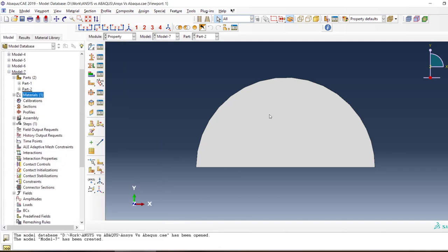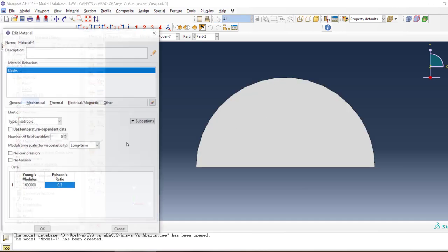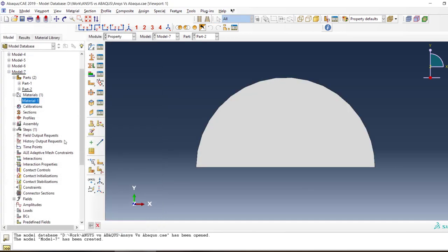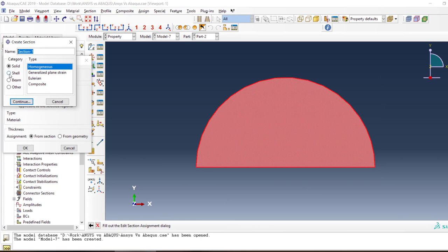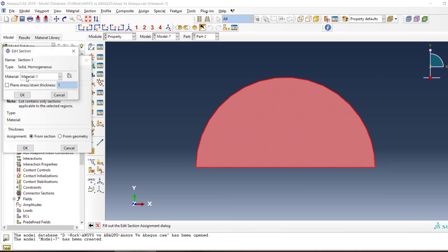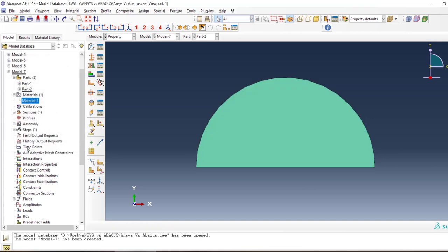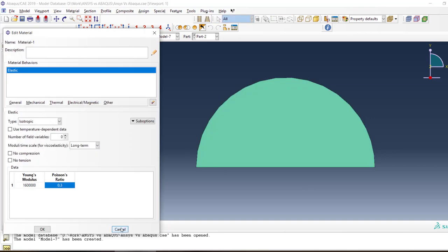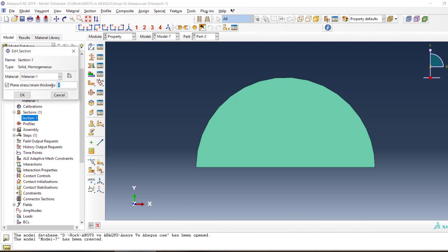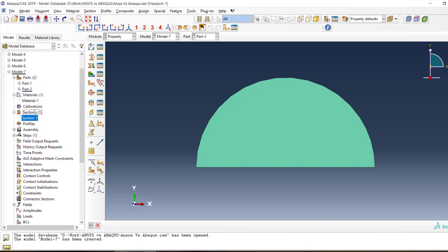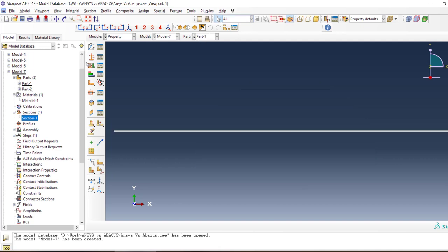Now because this is a 2D problem with frictional contact, it would have a significant impact by the Poisson ratio. So we apply the section that is solid homogeneous and material using the thickness, but I want to do something. I want to switch this thickness to be 6, and I want to apply the same thing to this beam as well.